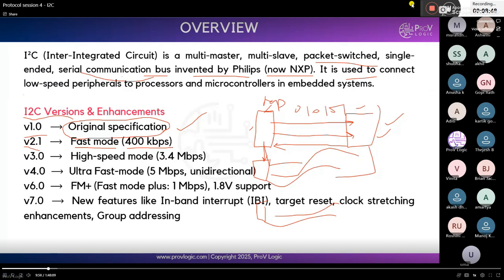And in I2C, we have a clock. If you see in your UART protocol, we don't have the clock, right? How does the synchronization happen between master and slave? Through the baud rate. The master side baud rate and slave side baud rate need to be equal. Both baud rates should be maintained at the same clock frequency, and then we communicate with each other. But in the I2C protocol, we don't have any baud rate. Directly, we communicate through the clock, master side and slave side. Okay. Clear till here? Any doubts?